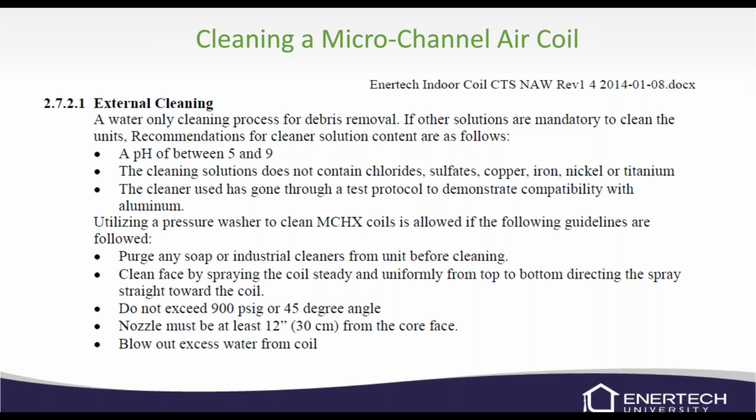So again, that's why we say don't use them during construction. For one, it can void your warranty. And for two, if you get any kind of lacquer or paint or drywall dust, you're going to have a hell of a time trying to get it clean. So the best way to clean a microchannel coil is to not have it get dirty in the first place.